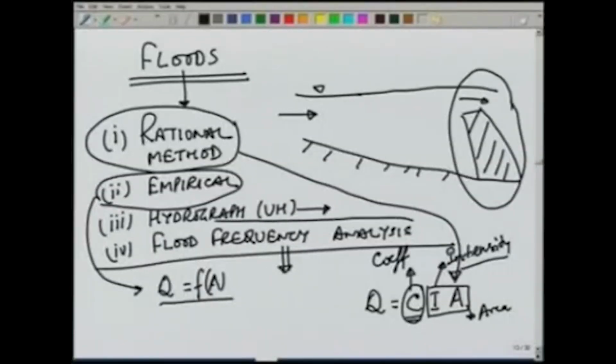So, these aspects come into the picture, and therefore flood frequency analysis becomes very important. It also gives us an idea about the risk involved in the design. A little later on, we would look at risks and reliability: what is the probability of failure of a structure within the next 10 years or next 50 years, what design flood to take for its design, and how to find out what a 100-year flood is, because we may not have data available for a 100-year period.